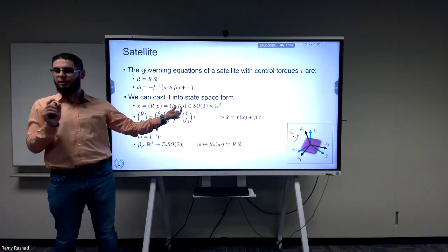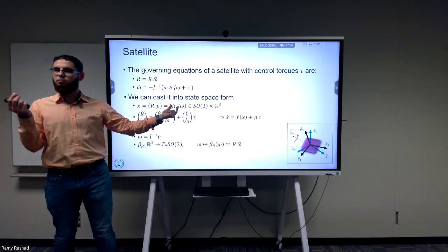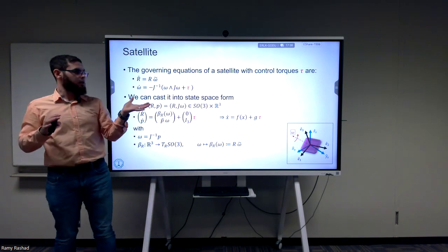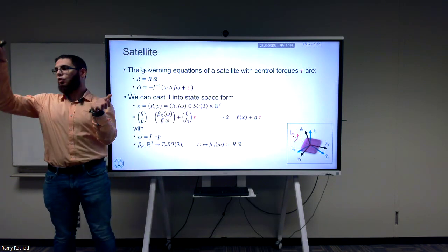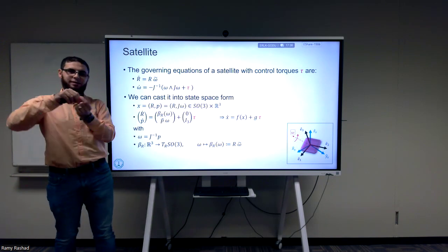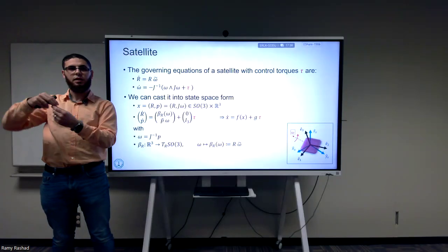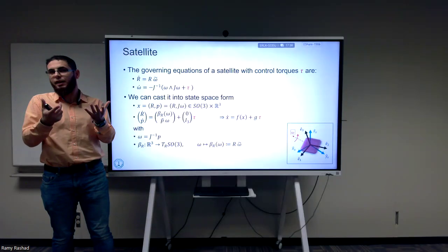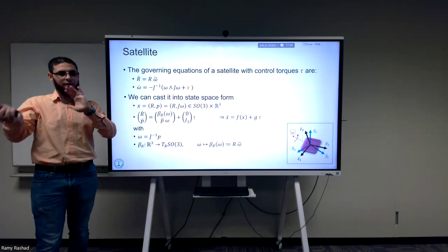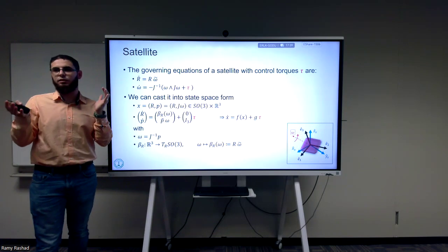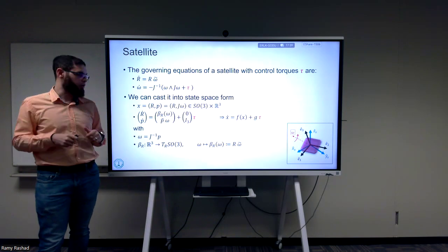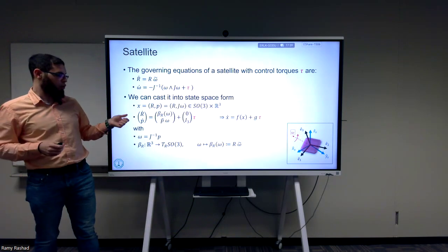To be precise, the momentum is a covector, so it should be on R3 star, but it doesn't matter if I write the momentum as a vector or covector. In the end, it's just the momentum. I'm writing the momentum here as a column vector, but we mean it's a covector in nature, because it changes coordinates differently. We don't see that in SO3. If you remember, we never saw that momentum and velocity change coordinates differently, except when we went to SE3. In SO3, we're always changing in the same coordinates. Something to go revise.